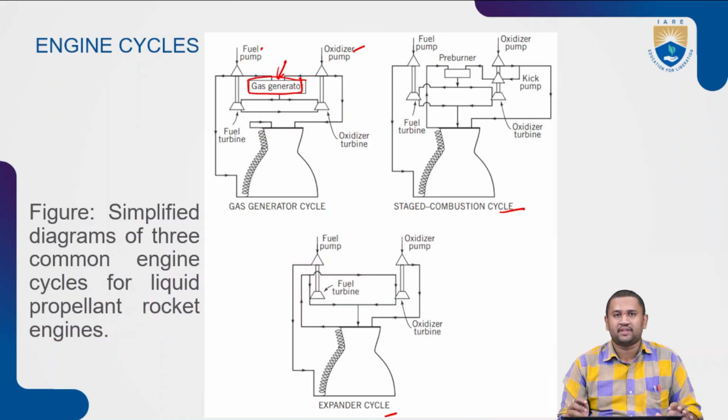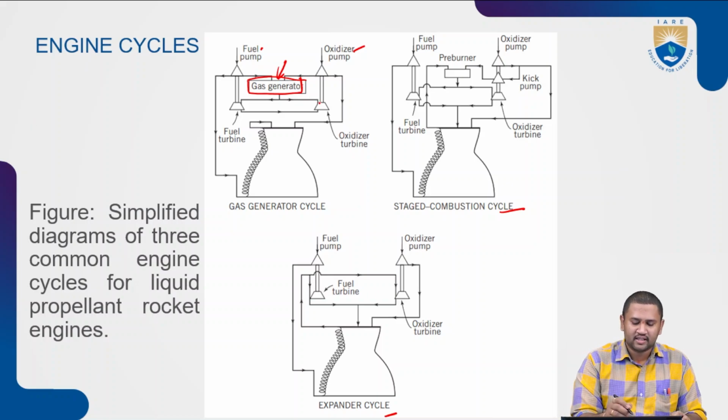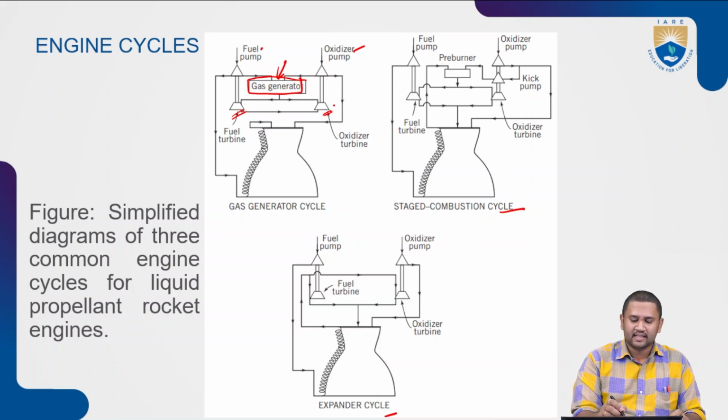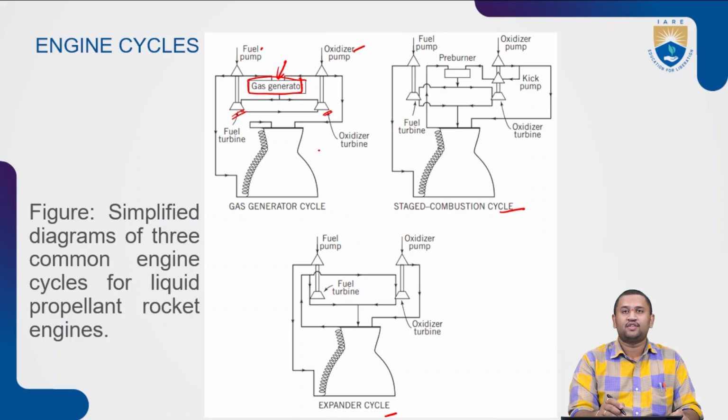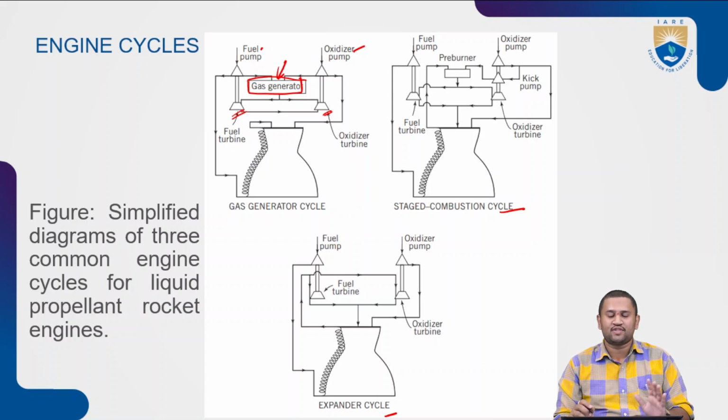Small amounts of fuel and oxidizer combined give out a huge amount of high enthalpy gases that are redirected towards the turbine. These gases are then sent back towards the nozzle, or based on the pressure ratios, we can directly leave them out to the atmosphere.